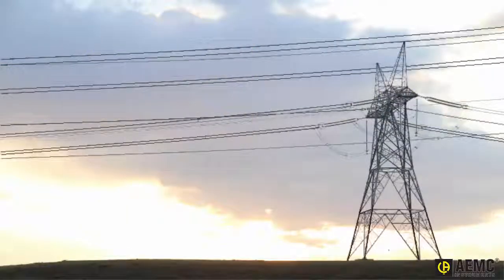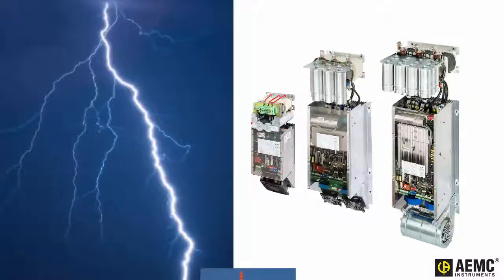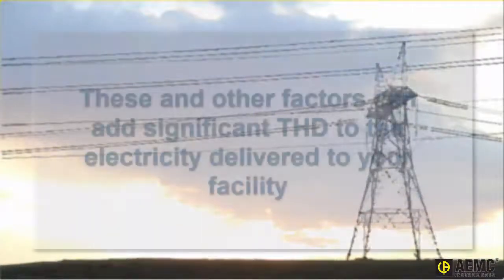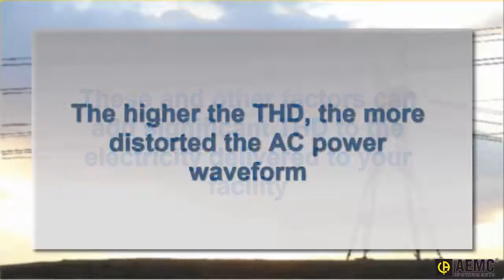In an electrical power line, a number of factors can create harmonic distortion. These include currents introduced into the line by users of nonlinear loads, environmental causes such as lightning, electromagnetic interference, and others. As a result, the AC electricity delivered to a facility can include a significant percentage of THD, in addition to the fundamental sinusoidal electricity produced by the power generation plant. The higher the THD, the more distorted the electricity's waveform. This can be a problem for electrical equipment designed to operate optimally when provided with clean, undistorted AC power.